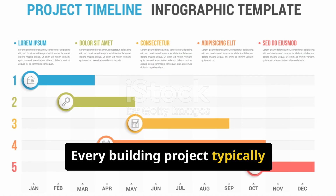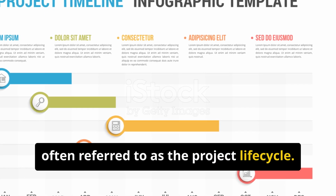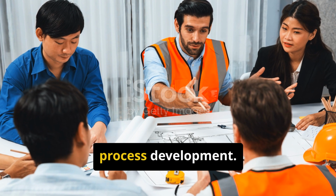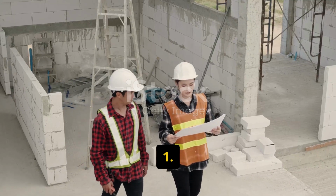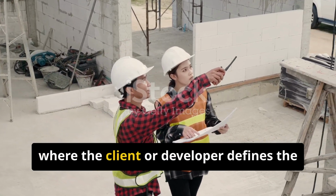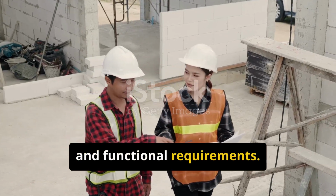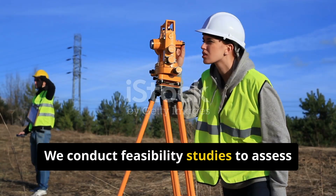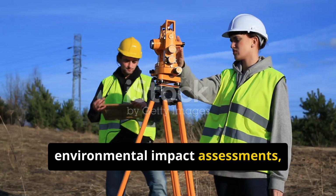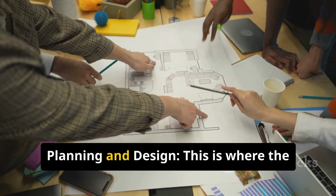Every building project typically progresses through distinct phases, often referred to as the project lifecycle. Understanding these phases is the first step towards mastering construction process development. 1. Conceptualization and feasibility. This is the initial stage where the client or developer defines the project's scope, objectives, and functional requirements. We conduct feasibility studies to assess the project's viability, including site analysis, environmental impact assessments, and preliminary cost estimations.